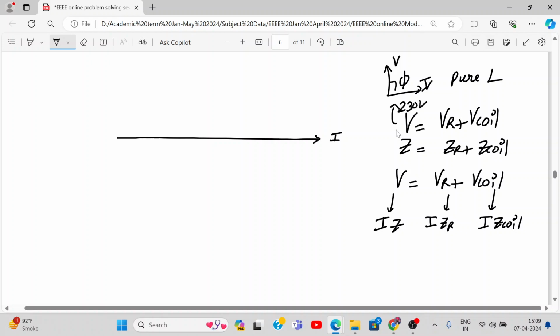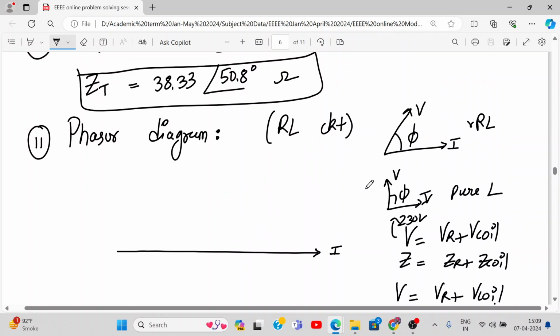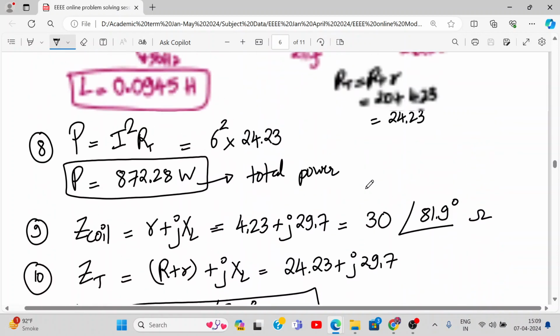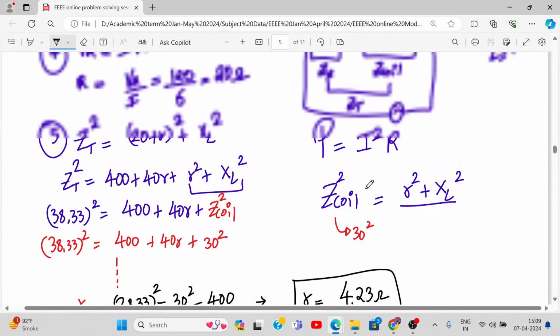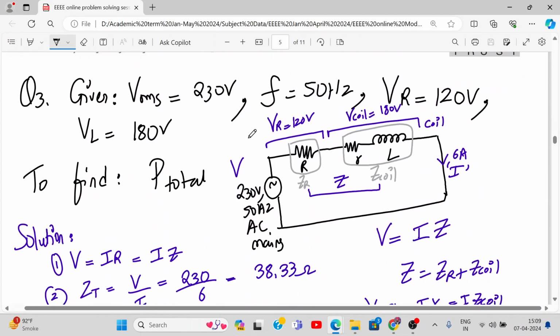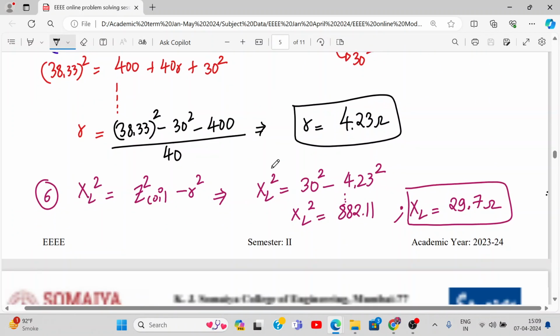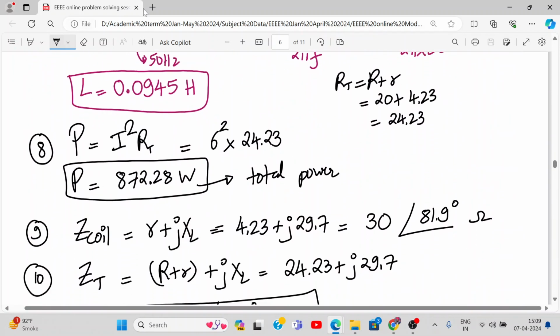How will you add? No, this is a single phase circuit. This is single phase. We can use root 3 VL I cos phi for 3 phase circuits. Do you get it? Yes, you have the formula for power as VI cos phi. You can use this.